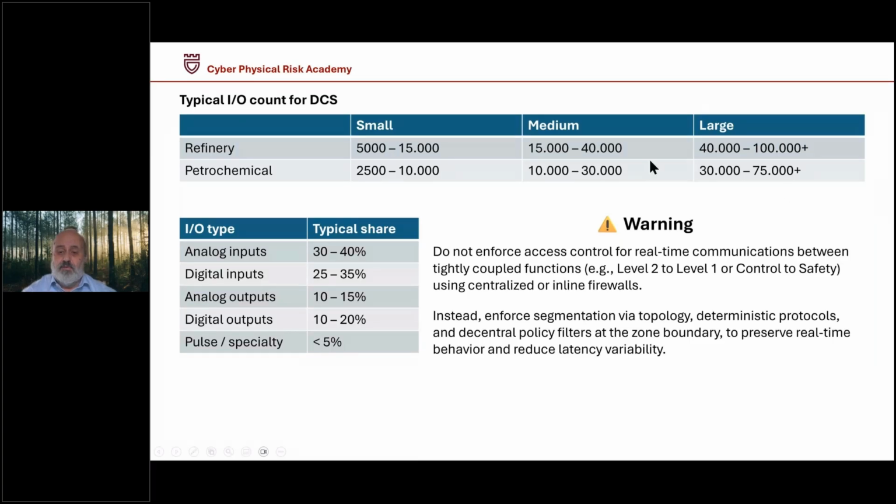And this is the reason why you should always be careful on these level 1, level 2 segments that you do not have too many filters in there. It's a balancing between minimum privilege, what some of the ISA requirements ask, and the real-time performance of the system. ACLs delay traffic. ACLs create latency, create jitter.